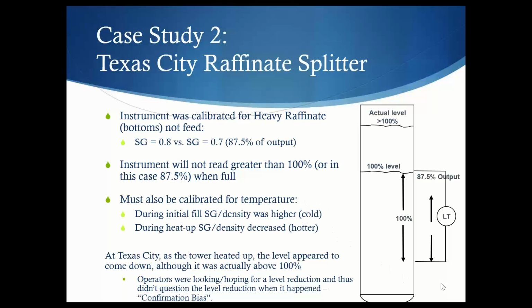The other thing is that it needs to be calibrated for the temperature. If it's calibrated for colder fluid, the density will be higher, and if it's hotter, the density will be less, and so there'll be an error there as well.